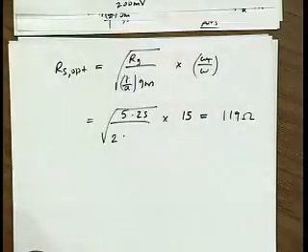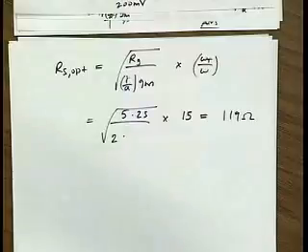Questions? Yes. The F min equation earlier, over which frequency does that equation hold? From DC to omega t? Certainly not till omega t. If I had to give a conservative estimate, I would say omega t over 10, but you can probably use it up to omega t over 2, and it's reasonably valid.